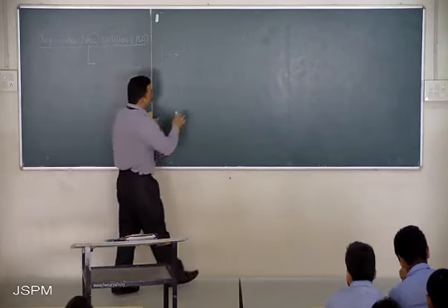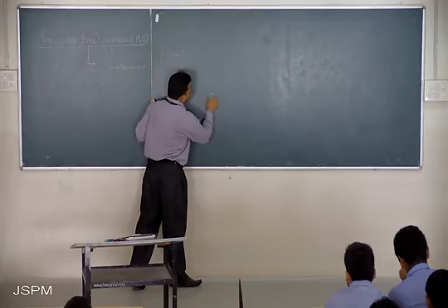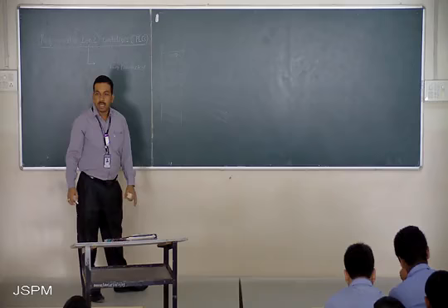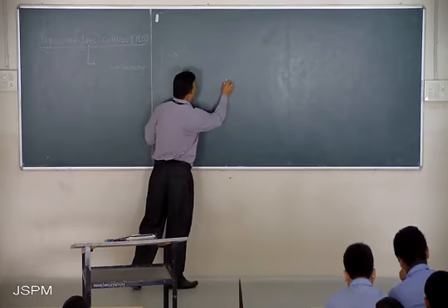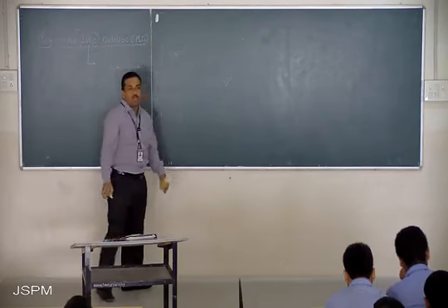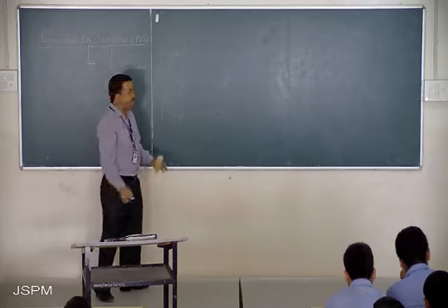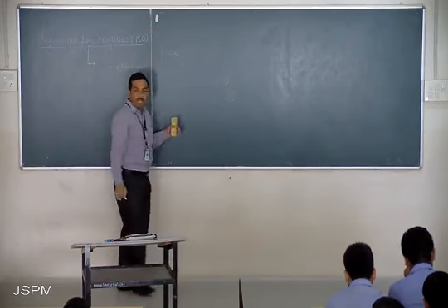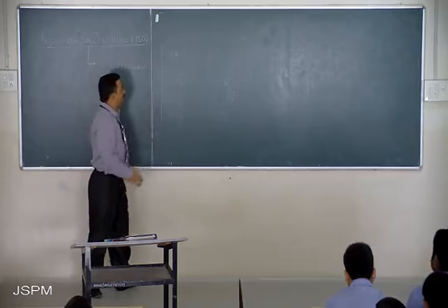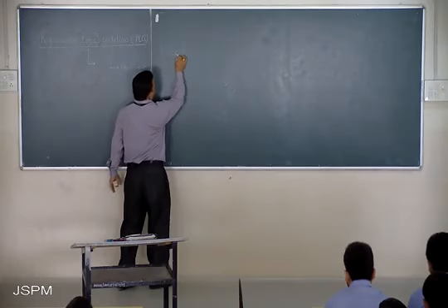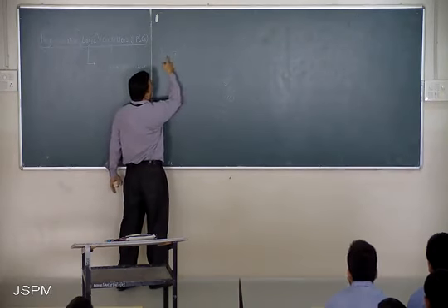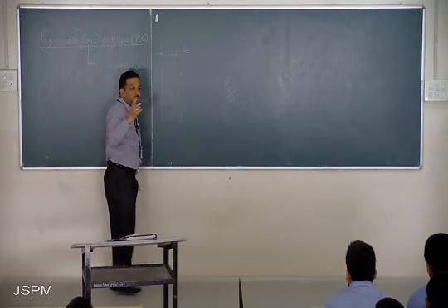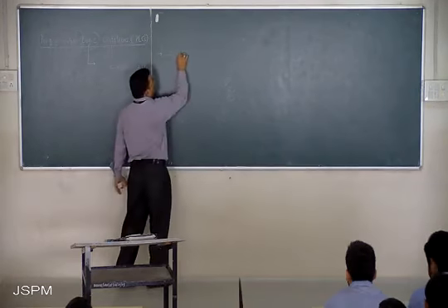It is very similar to programming, where we write down the program through sentences. This particular logic will be resolved, then the second logic will be resolved, then the third logic will be resolved. Very similar to that, in the ladder diagram also, the processing happens like this. First, the logic related to rung number 1 will be resolved and the output will occur.